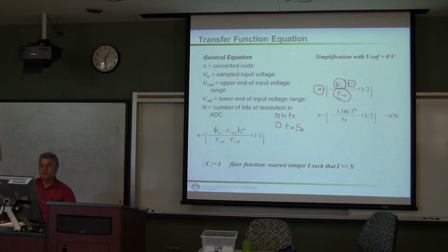And it just so happens that when I'm recording this measurement, it's going to be 3.3 volts. With my formula, by the way, this handles our rounding, because you combine this plus 1/2 with this function, which is take the floor, which is basically the equivalent of rounding.